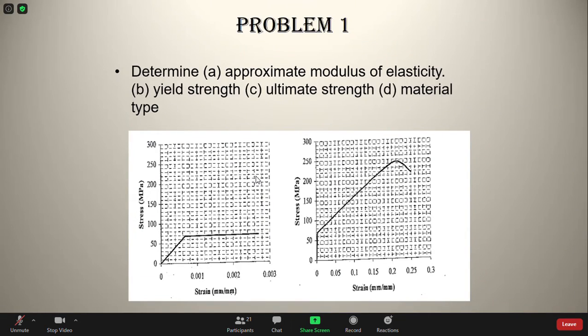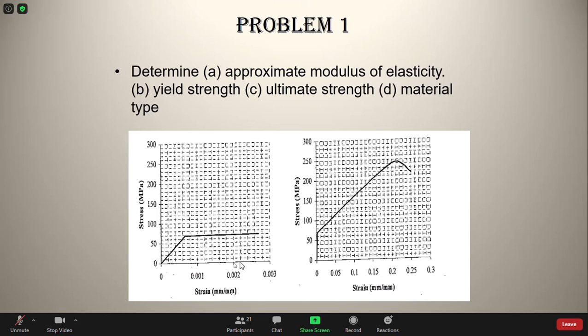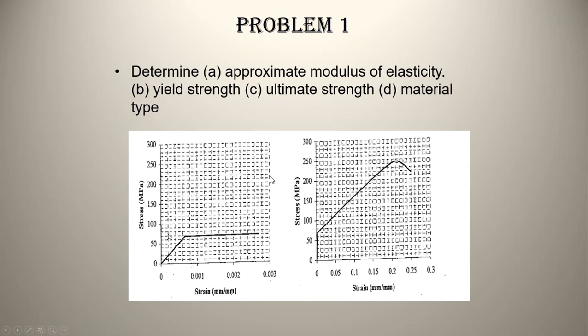Well, you go to the graph and you go to 0.2%, which is this point, and there you plot a line parallel to this line. When you do that, you'll probably end up on the same line. So this is the value you have to read off. How much is that? If this is 50, this would be 70 megapascals.